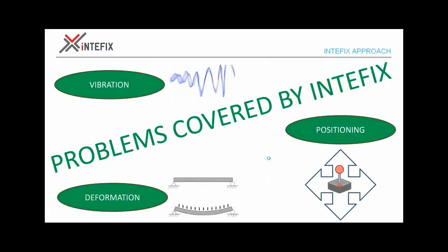Well, regarding the problems covered by the Intefix project, as I said before, it is related to machining processes, and three common problems in machining processes are the vibrations, the deformations of the workpiece during the process or previously due to the clamping forces, and also the positioning of the workpiece within the machine volume or within the fixture itself.